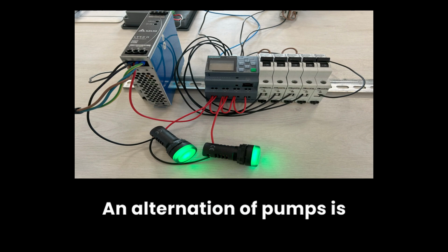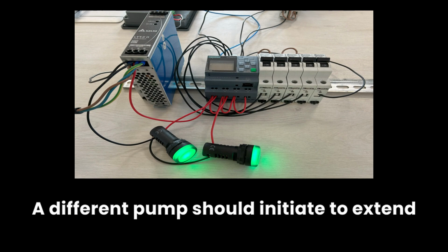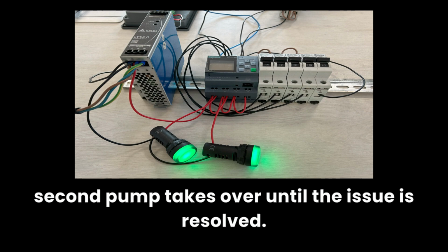An alternation of pumps is necessary. With each new start, a different pump should initiate to extend the working life of the pumps. If the pump scheduled to start encounters an error, the second pump takes over until the issue is resolved.